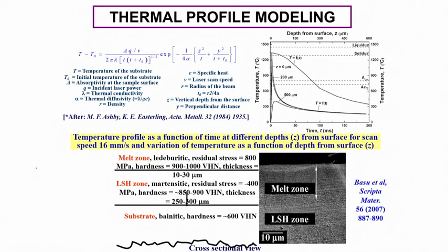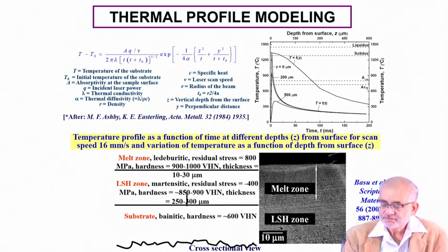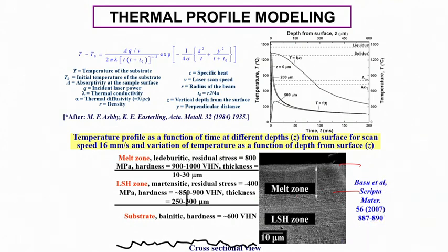So in order to do that, it's important that we make sure that surface melting is avoided. If you form surface melting, then you end up getting a higher amount of carbides, but more importantly, this region, because of the shrinkage suffered during solidification, may develop residual tensile stress, which is what we don't want. So either you grind off this portion or make sure that your heating process is not going to cross the solidus line.